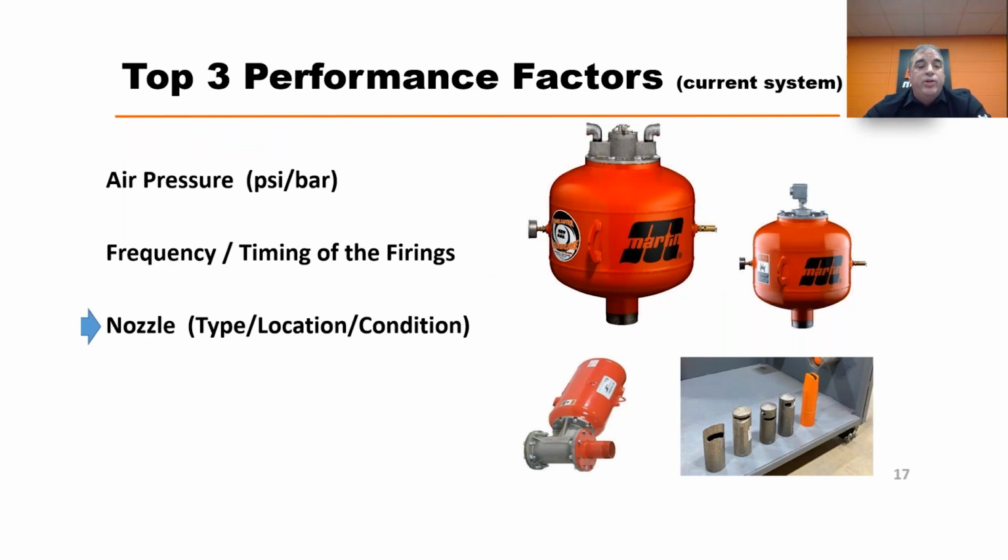So we've talked about air pressure and the frequency and timings of firings, and the biggest thing is nozzles. You've spent your money on an air cannon, getting it put in the right place, using the right type of nozzle, and then even the condition of the nozzle as it wears or as the system works are all factors.